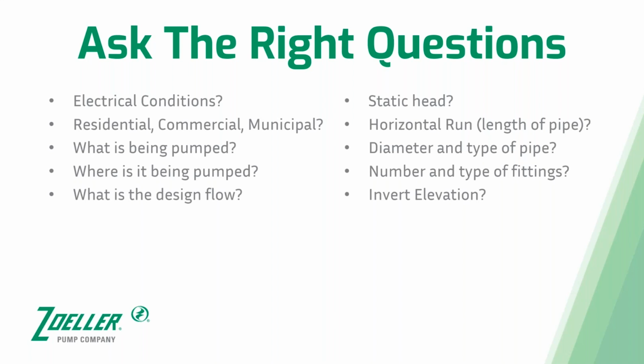You need to know what your design flow is. Specifically, what is the flow that your pump needs to be able to handle that is coming into that pump station? If your pump is not capable of handling that incoming flow, you can end up with your system overflowing or a backup occurring. You need to know your static head, so how high you're pumping from your pump to the outfall of your system.